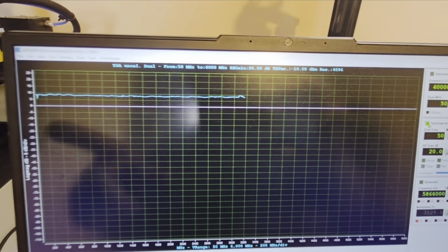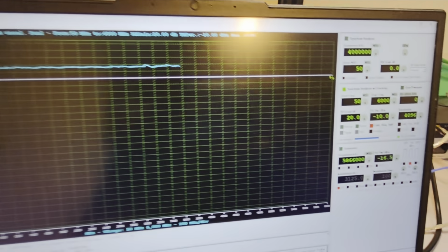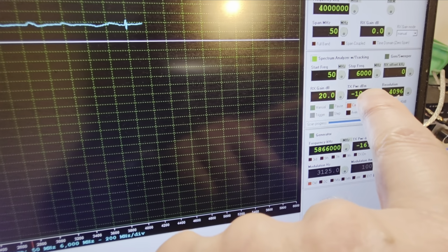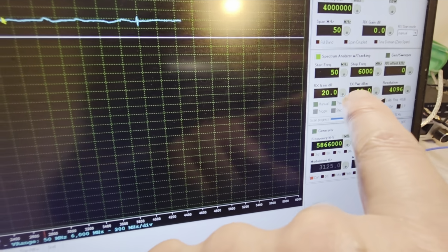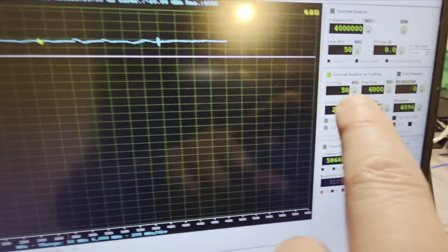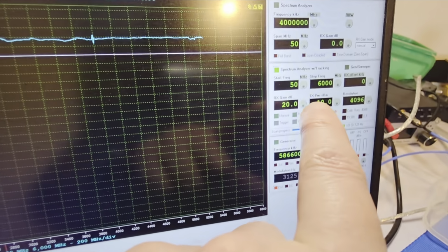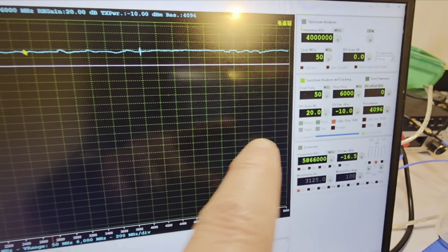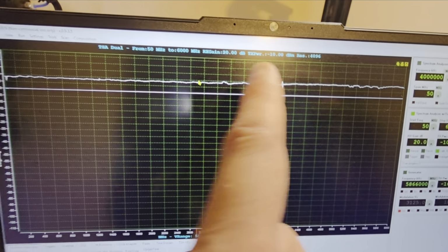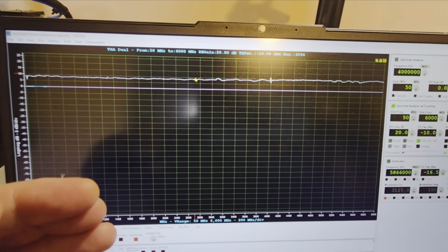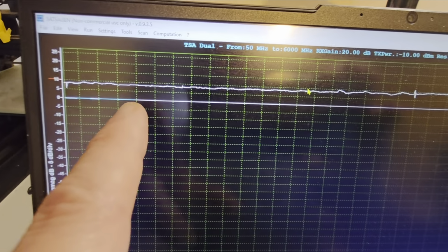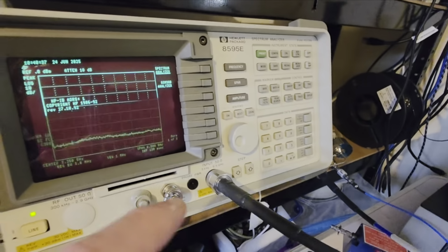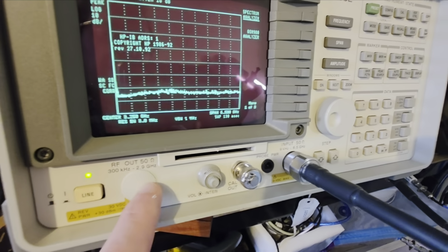So you see, it's making the first reading. I have plus 10 decibels because I have power at minus 10. I could get 5 more, and RX is at 20, so the difference is what I'm getting here. I could get maybe 5 decibels more, maybe 10 in some areas, especially under 4 gigahertz, but I'm looking for flatness. So now, do you see? It's making the zero. It's normalizing like a real spectrum analyzer that has a tracking generator. This one doesn't have the option.